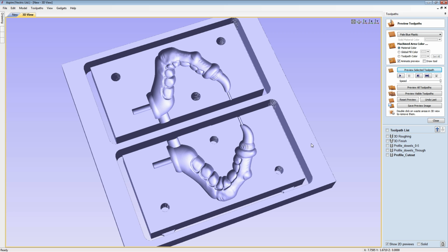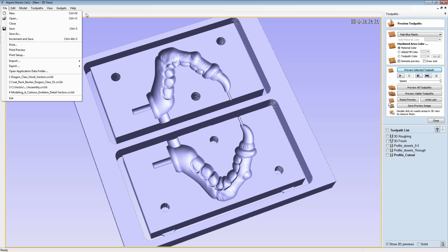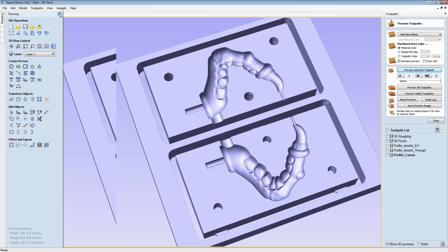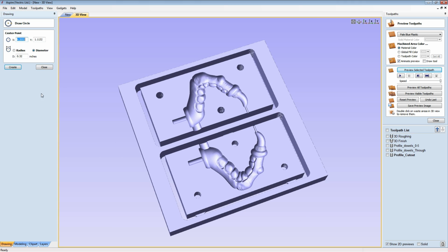There's another question there about going over the calculator with millimeters versus inches again. So if I just go over to the drawing tab, in order to convert something from metric to inches, first of all I'm working in inches here, so I would like the values ultimately to be in inches. Let's say we had a 10 millimeter circle we wanted to draw. I might come into the circle tool like this.